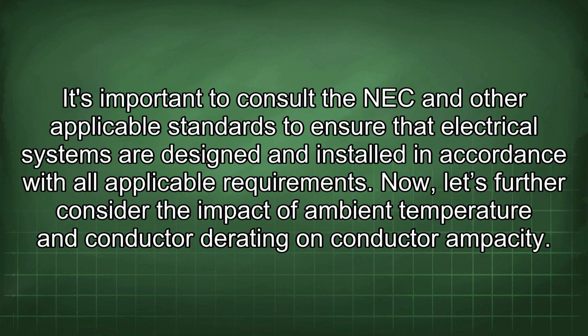It's important to consult the NEC and other applicable standards to ensure that electrical systems are designed and installed in accordance with all applicable requirements. Now, let's further consider the impact of ambient temperature and conductor derating on conductor ampacity.